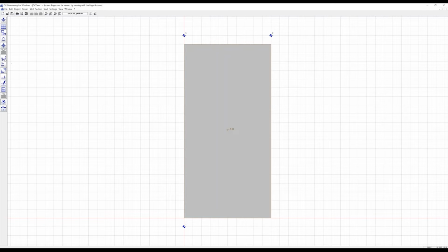We can as well define section lines. For example, one through the foundation pit. This can be a polyline, and we stop the input for this line with the right mouse button. So we have section 1 here, and another section line through the wells. This should be section number 2. Now we can switch to the graphics to see the results.